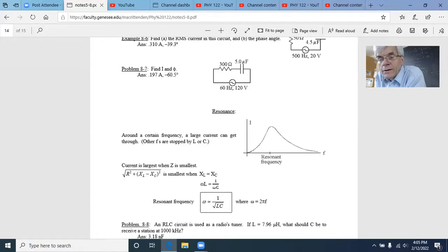But with an alternating current, all the electrons ever do is jiggle back and forth. So they don't actually have to have any place they can go. Even though the two sides of a capacitor don't touch each other, electrons can flow into the negative plate and then back out of it, over and over. So an alternating current can exist in a circuit with a capacitor because you just keep charging and discharging it over and over again. But to a frequency of 0, a capacitor is a broken wire, and so the current is 0 when the frequency is 0.